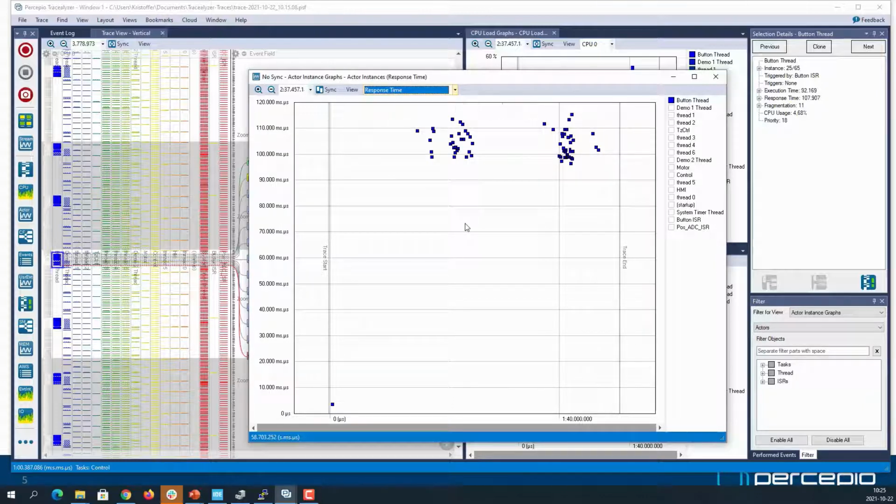And what is that? The response time is, let's say the example of you have some interrupt that is generated when you receive some data. And you have a task that is waiting for some lock, maybe a semaphore, and when the interrupt occurs, the interrupt routine sets the semaphore and it's time for the task to process the data.